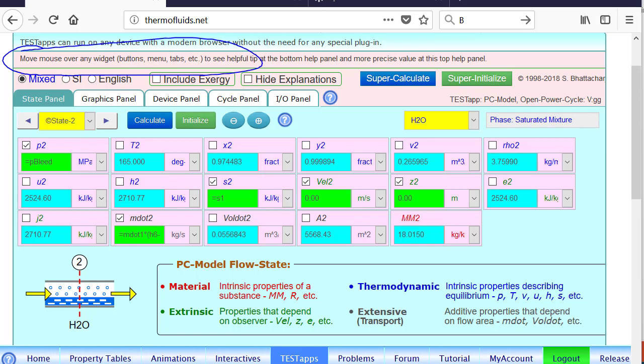Okay, now let's move on to state 3, which is the turbine exit state. Again, it's isentropic. By the way, the bleeding state is also isentropic, so I use that. It's isentropic, and the pressure is the same as the condenser pressure. And of course, m dot 3 is now written in terms of m dot 1 minus m dot 2. We want to keep our number of variables minimum, so that in case we want to change a variable, it's very easy to do a parametric study.